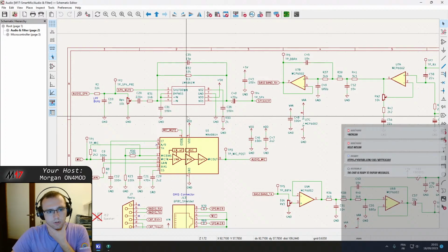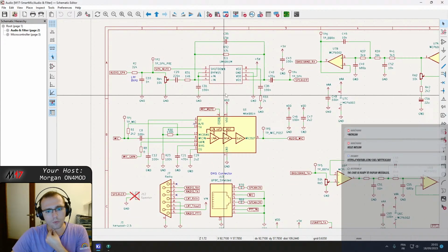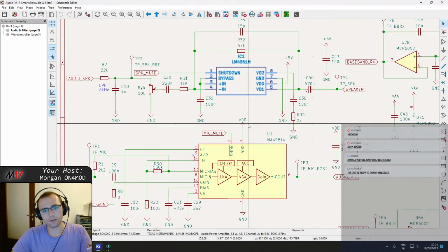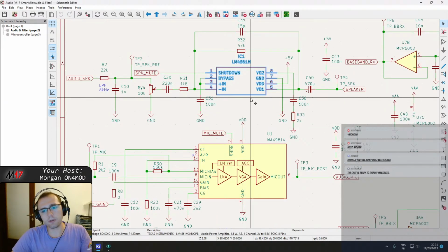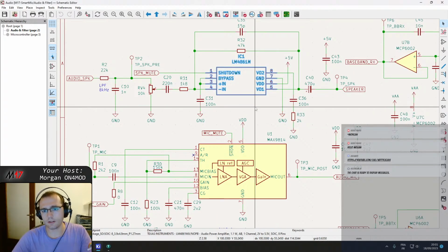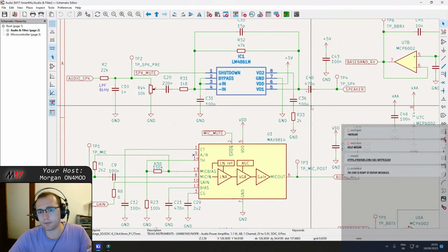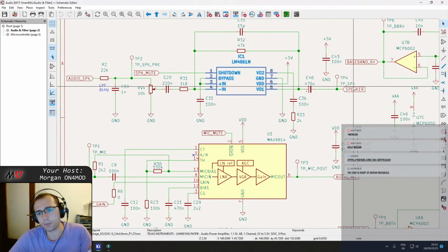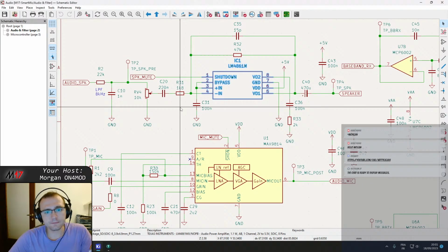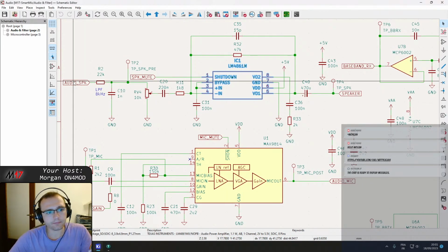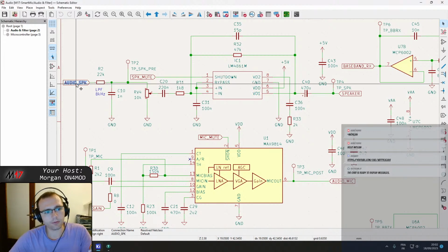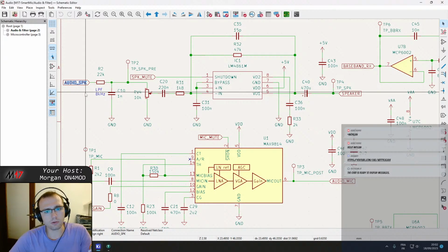On the audio, we have basically this, the power amplifier, which will provide the oomph, the power for the speaker, because the speaker is a low impedance input. The audio comes from here, which I think comes directly from the microcontroller.